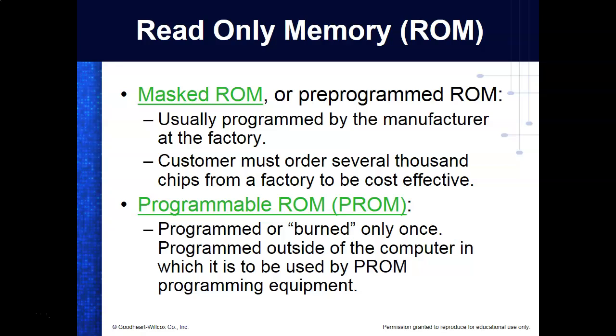That's the only thing the CPU knows what to do: go to a certain address every time and pull in an instruction. And then from then on, it's under the control of a program that was written by a person somewhere. So mask ROMs, we actually bought these with the programs in there. They were put in there when the ROMs were made, and these were in there for years.